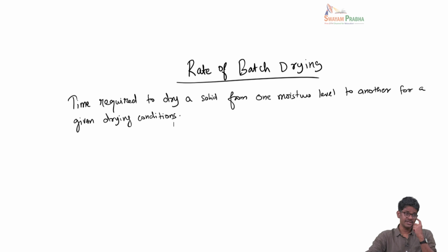Okay, by matching the drying conditions in the lab scale and in industrial scale and using a very small amount of drying material, you can look at what rate the moisture is removed from this material. Okay, so this is basically a lab drying test, and then based on this lab drying test we can infer some information, and we can use this information to scale up and predict what's the actual time required for a large industrial scale drying operation. Okay, so that's the strategy we are going to use.